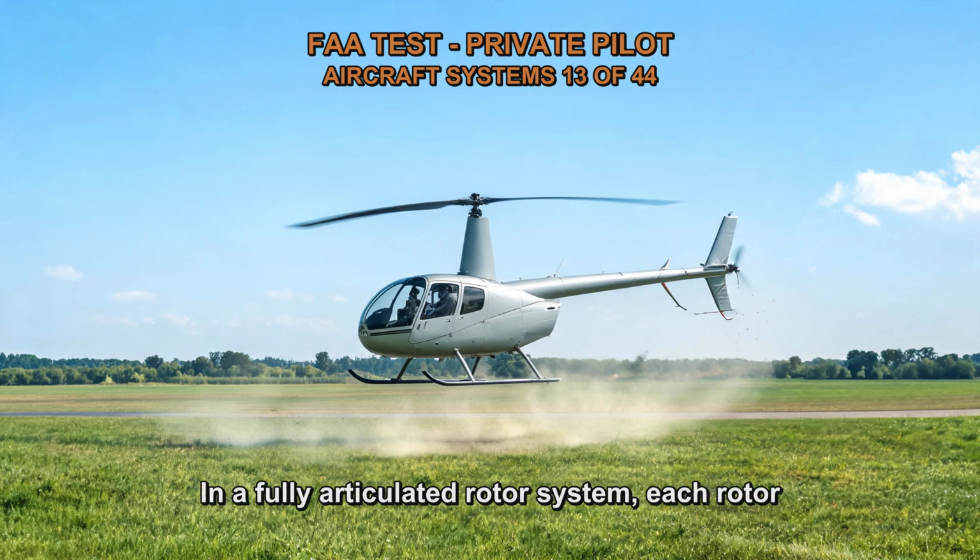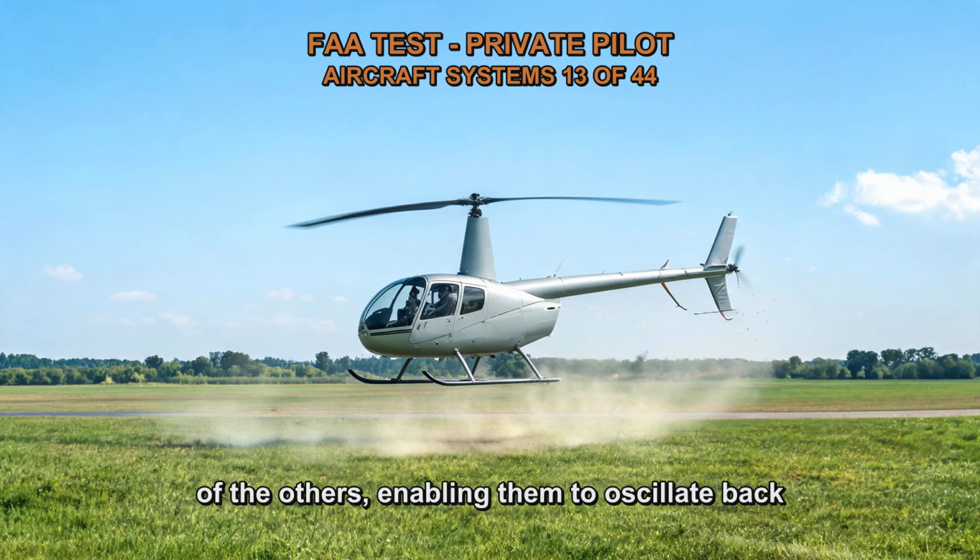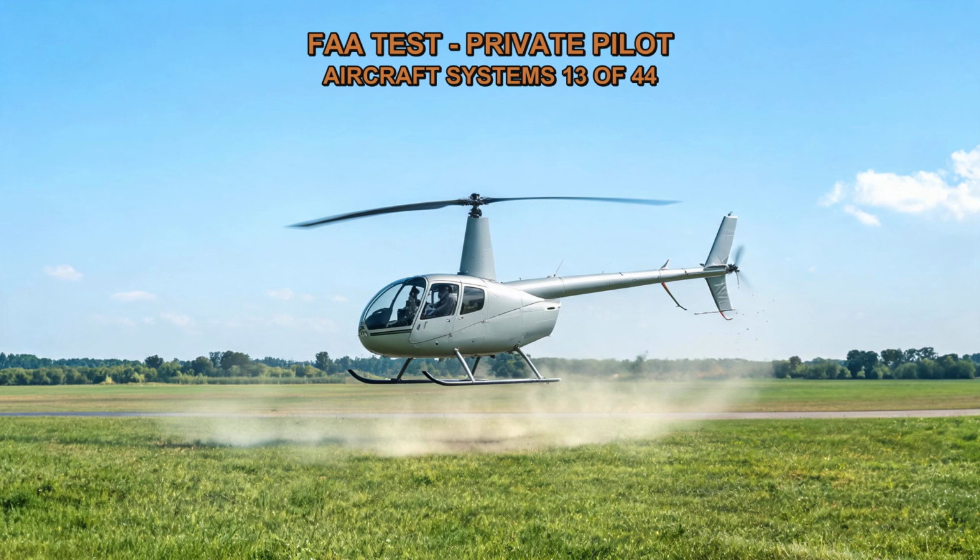In a fully articulated rotor system, each rotor blade is connected to the hub through a vertical hinge known as a drag or lag hinge. This hinge allows each blade to move independently of the others, enabling them to oscillate back and forth in the plane of the rotor disc. This motion is referred to as dragging, lead lag, or hunting.